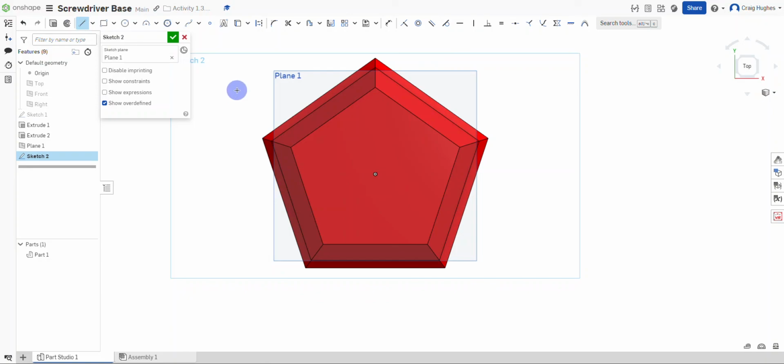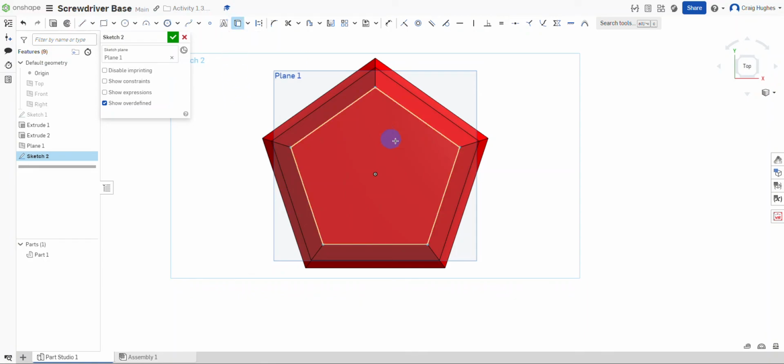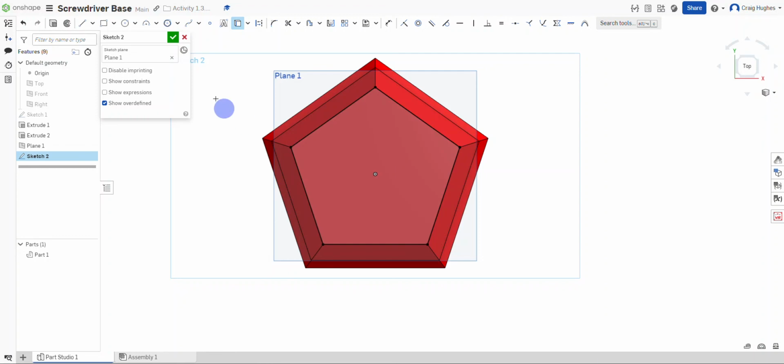So it usually is, but just to make sure, because some of the taper angles could be off by a little bit, what I'm going to do is use the Use Project option, and I'm just going to click inside of this shape, and you're going to see we get some bolded black lines that come up around the outside edge.